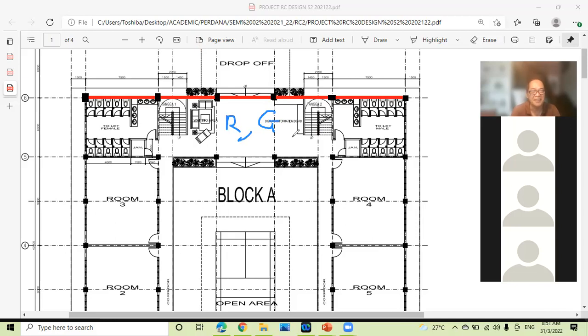We have our general guide. Remember dalam our notes on staircase, there is a formula given where a combination of R dengan G2 should be within a certain range, kan? So we can make use of that for a public building to guide ataupun to obtain some dimensions of R and G. Okay, so this is the basic architectural drawing.